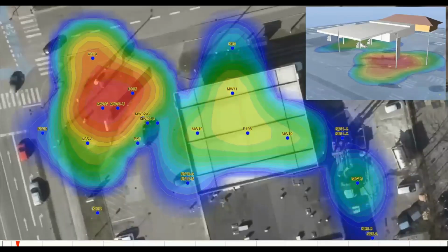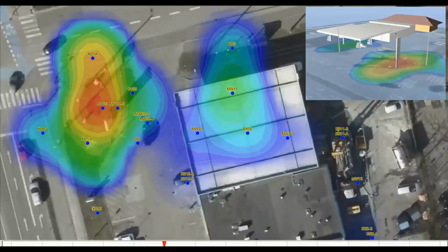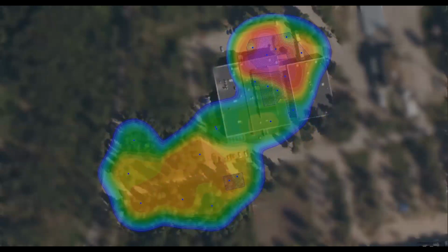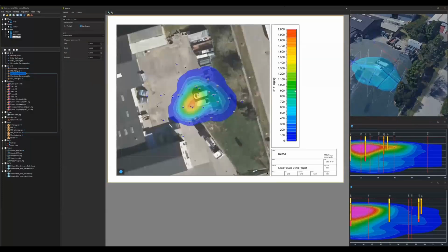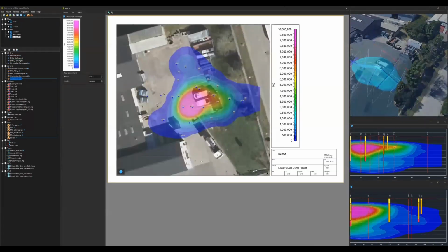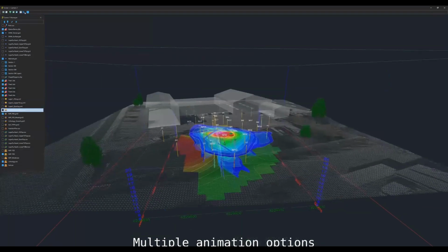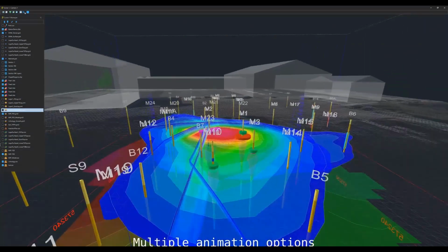By opening up the borehole, then we were able to fill it again with bentonite pellets and grout. And directly after the hole got fully sealed, then we would go again with the direct push tooling and start injecting at the required depths. So that's how we use that technique to expedite the process in challenging geologies.